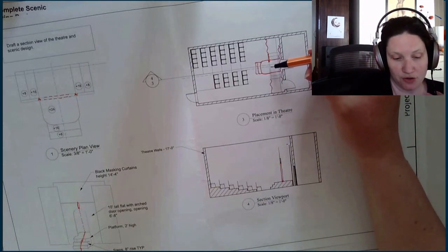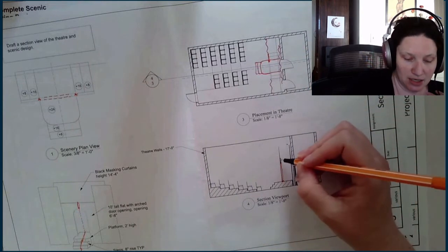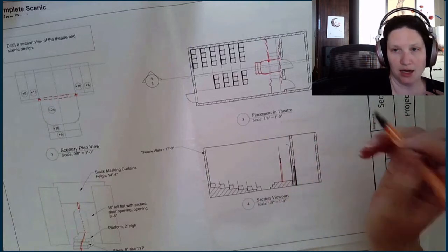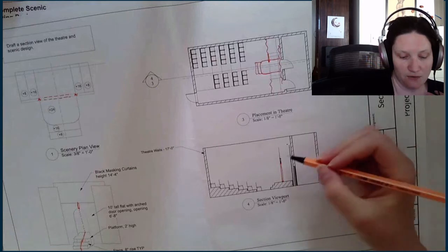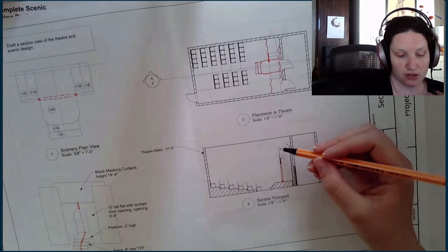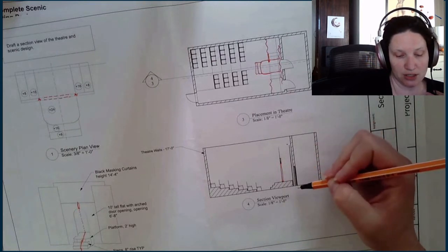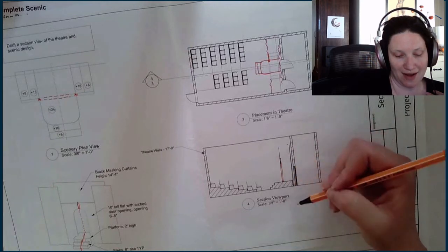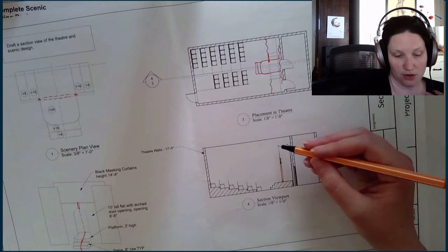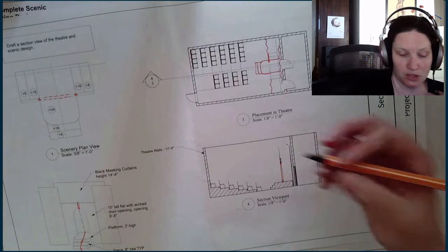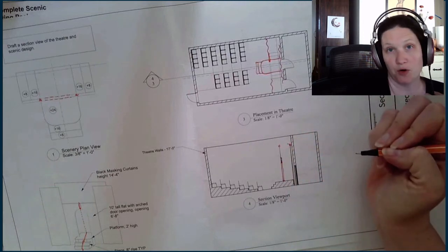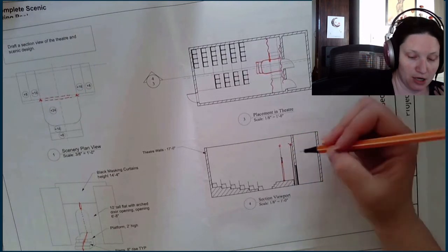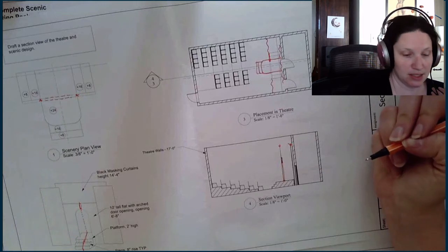So you're looking through the side of the archway, you'll see the opening of the door, and then you'll see this very small top portion with solid lines with diagonal lines for the thickness of that wall. You'll also see drawn here, the curtains have some fullness, so they're drawn sort of out. You don't need to do that. You can just draw those curtains as a line. If you wanted to put a little circle at the top of it to indicate a pipe, go for it. Be my guest. But your curtains can just be drawn as a line in this case.